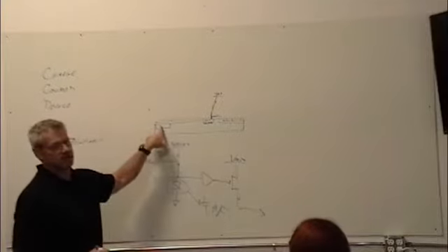Now, to do the same thing with a CMOS, each one of these is an effective diode, right? Negative, positive. I set up a diode, and I set up a reset, and then I have to have some way to store the charge. So I've got to build a capacitor here of some sort to store the charge.